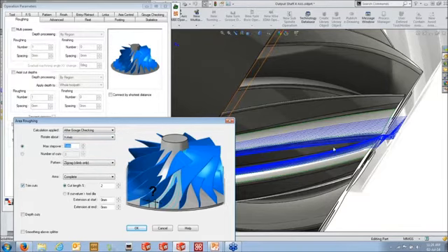We'll also trim a little bit away from the end of the edges here. So this option right here, the trim cuts, basically takes a small percentage of the toolpath away from the edges. Anytime you're approaching any of the boundaries, that's usually when you'll start to get some kind of weird loops or something like that. So we're just going to leave it at the default setting here, 2%, just to cut that away.